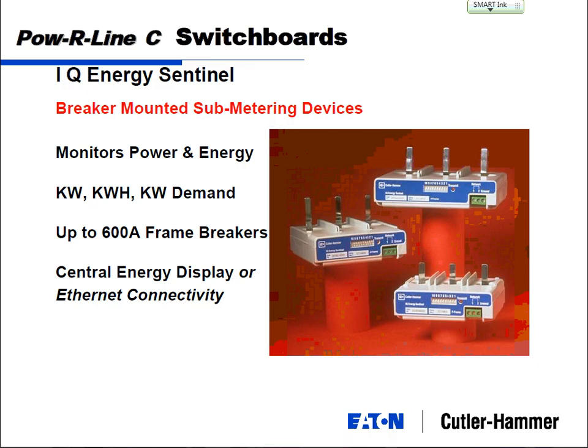One of the other things: the example I mentioned used those larger meters to monitor four different circuits. A lot of times you're going to have more than that. You build an office tower and you're going to rent out the entire first floor to different retailers, a Starbucks at one, a Subway at the other. You want to charge everybody for the energy they're going to use. You might have a switchboard where you've got 12, 15 tenants that you want to sub-bill out of that switchboard.